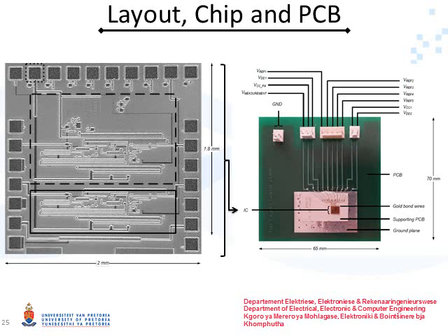The RF input and output bond pads should be located on the left and right side of the chip area respectively. Sufficient clearance between the DC wire bonds and RF pads should be provided. The minimum clearance distance set out by the infinity probes is 200 micrometer. This is to prevent the RF probes and wire bonds coming into contact. Any additional DC bond pads would interfere with the RF probes.